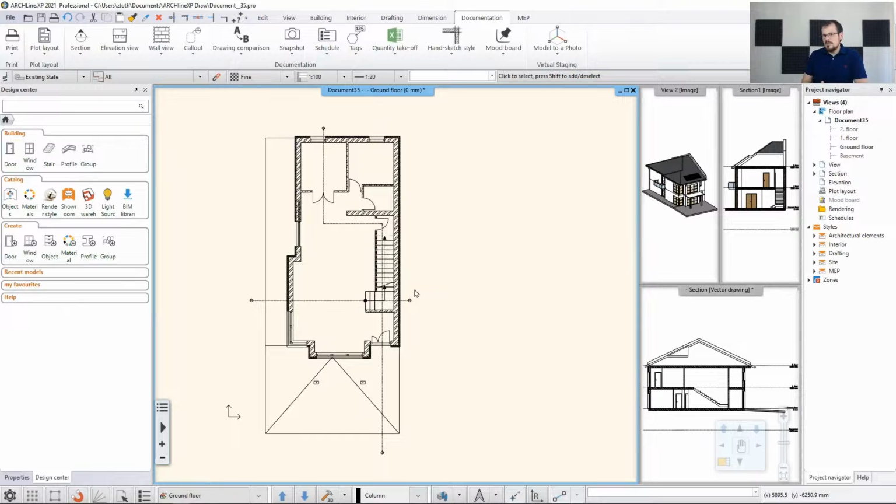This would be very important because later on I'm going to create some elevation drawings with shadows. I want to make sure that the shadows are accurate, so for that I need to define where the model is on the globe. And also I need to define the north direction, so the program would be able to calculate where the sun is shining from.